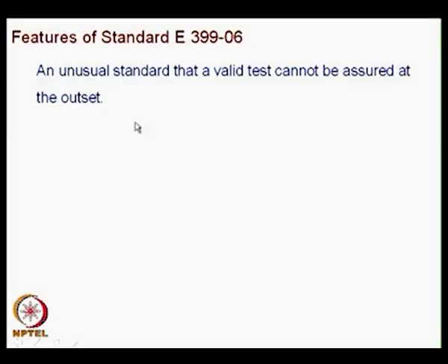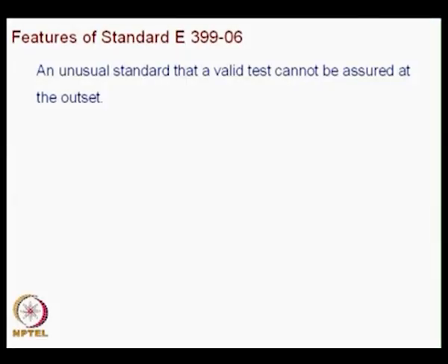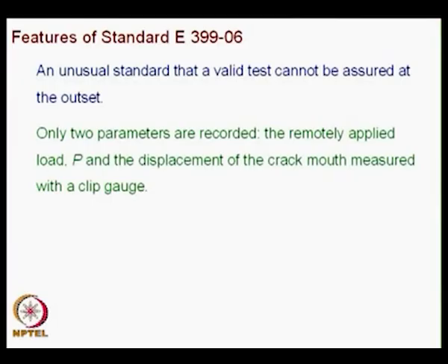it is an unusual standard in that a valid test cannot be assured at the outset. That we have seen, you have to find out KQ, and if KQ satisfies all your restrictions in terms of specimen dimensions, crack length, pre-fatigue cracking restriction and so on and so forth, then you call it fracture toughness. So, it is a very unusual standard from that point of view.